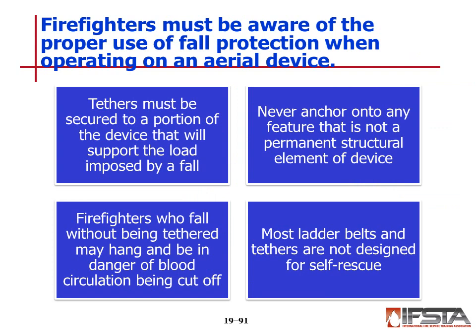Fall protection is only useful if the tether is secured to a portion of the device that will support the load imposed by a fall. Use only structural features of the ladder or platform for anchor points. Never use a feature that will allow the clip to slide more than a few inches. Never anchor onto any feature that is not a permanent structure of the device. Do not anchor to cables, wires, lights, or any other features.